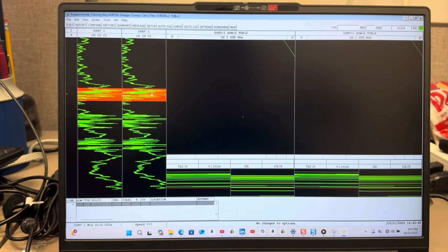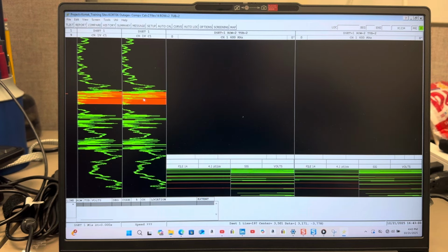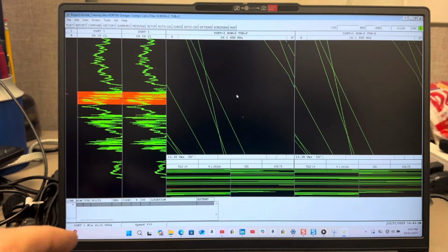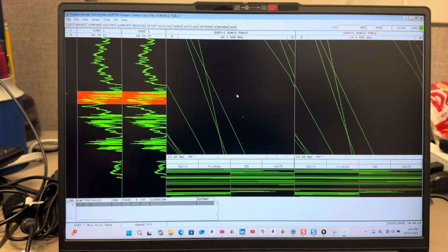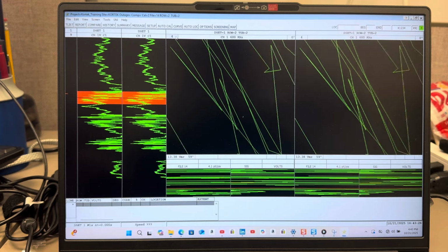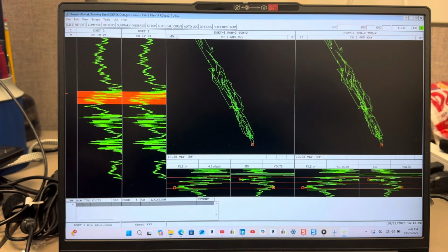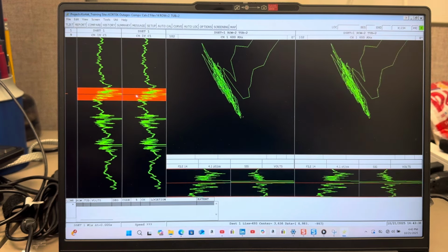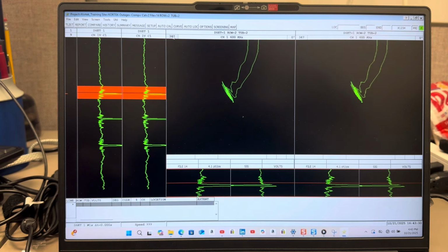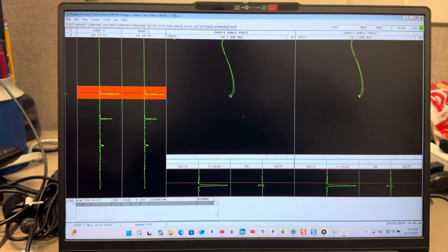Both have 600. But if I click over here in the strip charts and then put my cursor over here and click in the middle and hit the space bar, it balances the data. Now the data still looks way out of whack. That's because my spans are too high. So this little area that's got the 0 here, that's actually my span or gain control. So if I right click on that, it starts to bring that data smaller so I can get it on screen. And I have to bring it quite a bit yet. See how nice that data looks when I span it correctly?